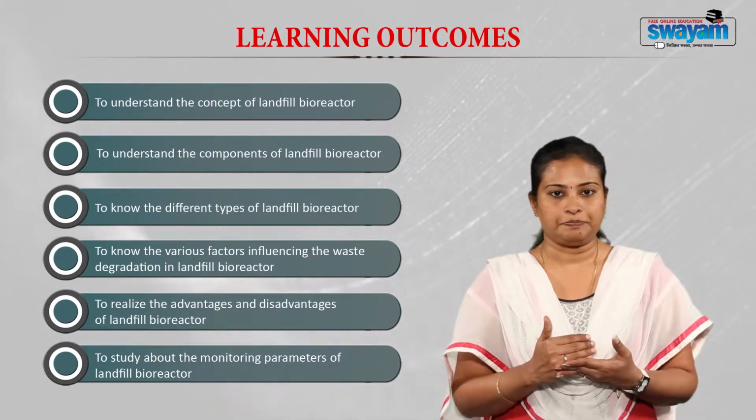Now, as I told you earlier, a landfill is an engineered structure where the waste is safely disposed of and contained to avoid environmental and health effects. They are usually made of cells in which a discrete volume of waste is kept isolated from adjacent cells by a suitable barrier. This barrier can be a liner.